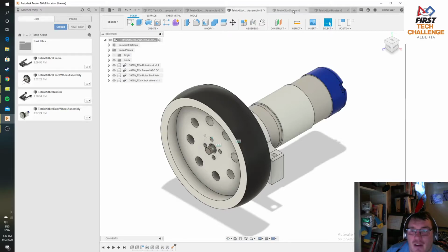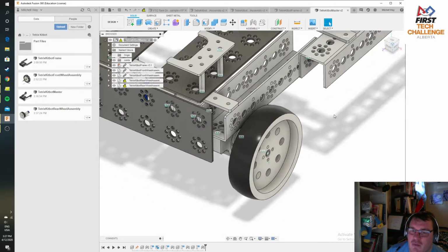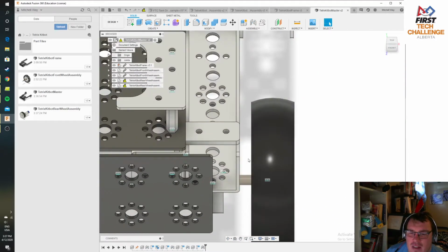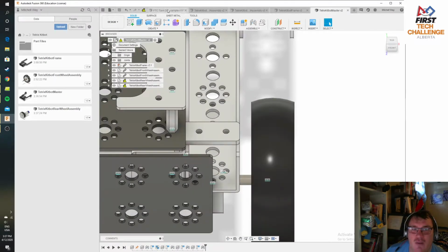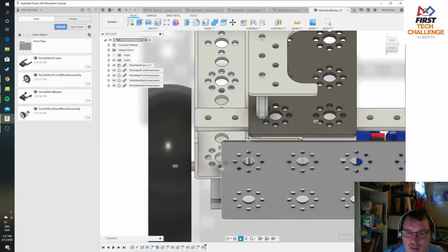But now I'm going to go back to my master here, which is the technical name for the file where I'm bringing everything together. Now you'll notice that this still has that same gap in there, but that I've got a whole bunch of exclamation marks up here. This is going to allow me to click my Get All Latest. It's going to go into my file system, grab all the part files I have, and move the parts into place based off of the new files. And you'll notice that that happened on both sides of this drawing.